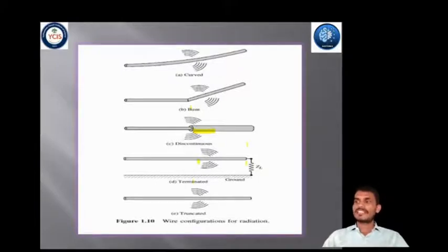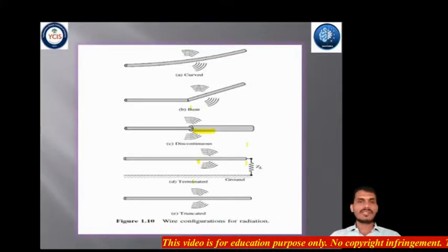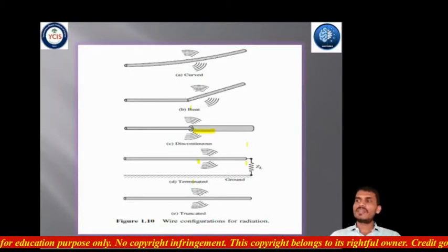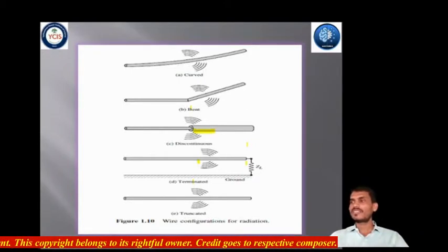Therefore, charge acceleration due to the exciting electric field, and deceleration due to the impedance discontinuity, are the mechanisms responsible for electromagnetic radiation, while both the current density Jc and the charge density qe appear as source terms in the Maxwell equations. In microwave technology, we discussed some Maxwell equations last semester also. We can refer to this reference book for understanding the Maxwell equations.